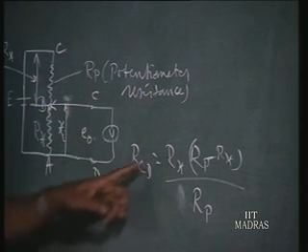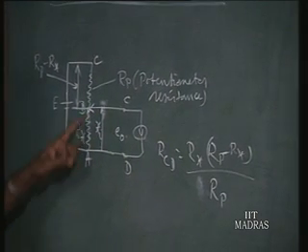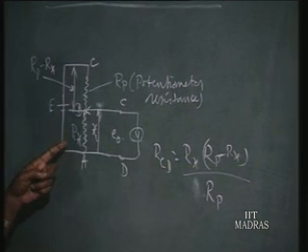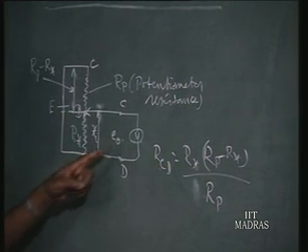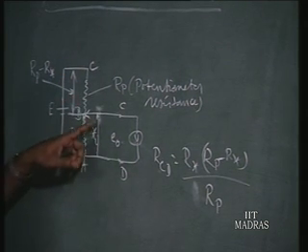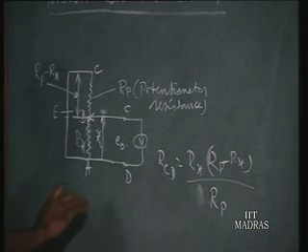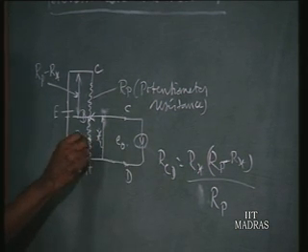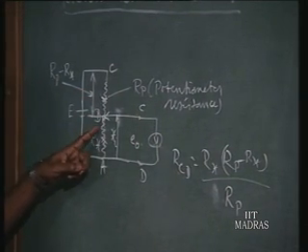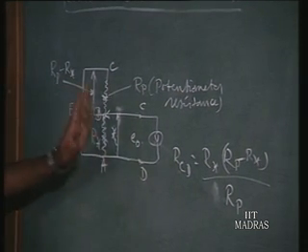Now what is the property of this RCD? As we vary xi, the input displacement, Rx is varying. Since Rx is varying, RCD is going to vary. So in selecting this voltmeter, you have to see what is the maximum value it can have. Maximum it can have Rp, so naturally you go for 10 times Rp. But if it is varying between 2 intermediate points, then for the particular application we are supposed to find out the variation of RCD, and accordingly you have to select it.